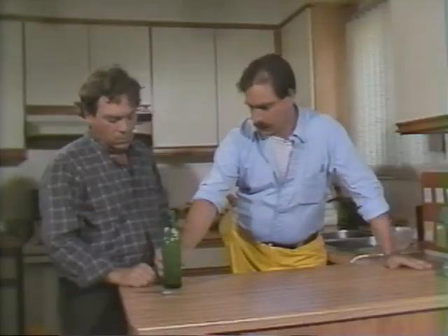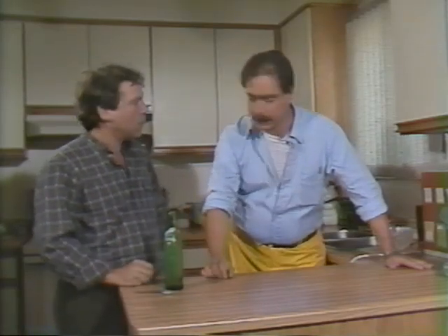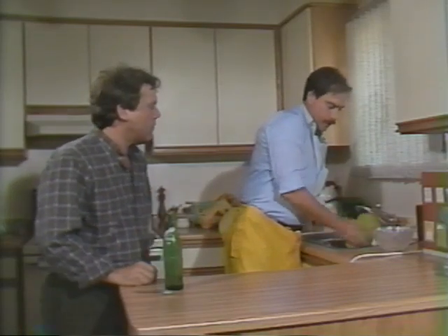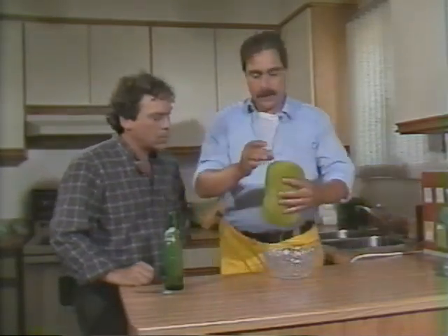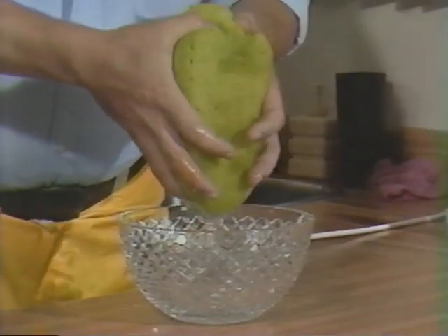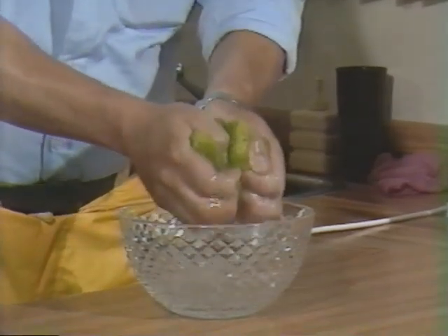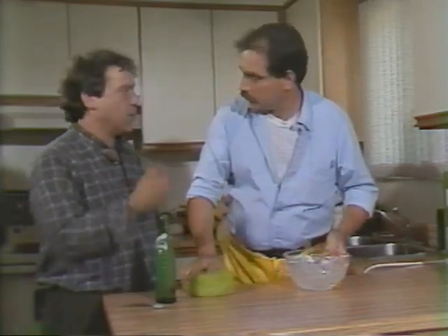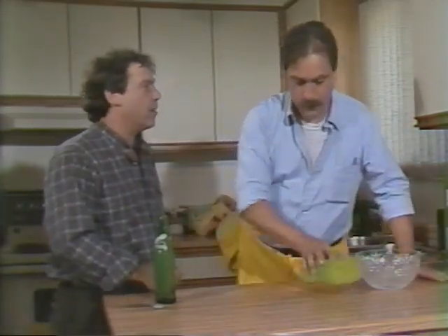When that humidity becomes a problem for us is when it condenses on surfaces. And that occurs whenever the air that's carrying it is chilled. For example, on this bottle where it's starting to condense now. Now, the reason that that takes place, if you would imagine this sponge as being the air, the ability of the sponge to carry water is reduced as the air gets colder and you drop that water out on the cold surface. Examples? Yeah, well, all around the house, I guess, when you're having your shower on the cold bathroom window.